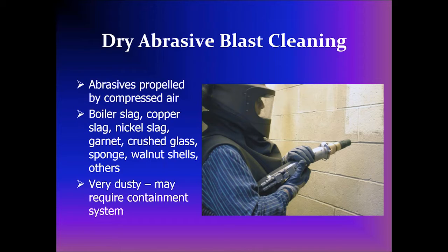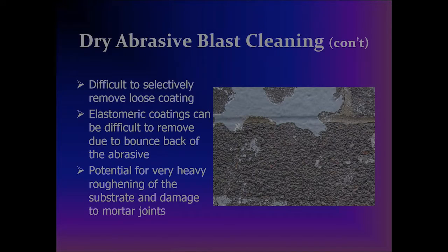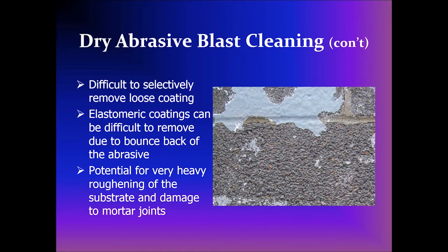Different types of abrasives are used depending on what you're removing or how aggressive or non-aggressive you want to be. And it is a very dusty operation. It may require some containment. I mentioned the fear of roughening it. Here's an example of CMU block abrasive blast cleaning.